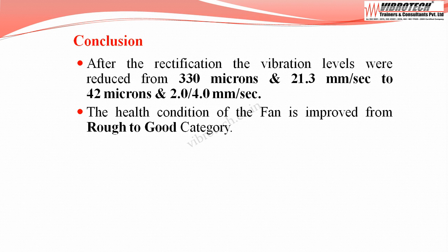After the rectification, the vibration levels were reduced from 330 microns and 21.3 mm per second to 42 microns and 2.0 to 4.0 mm per second. The health condition of the fan is improved from rough to good category.